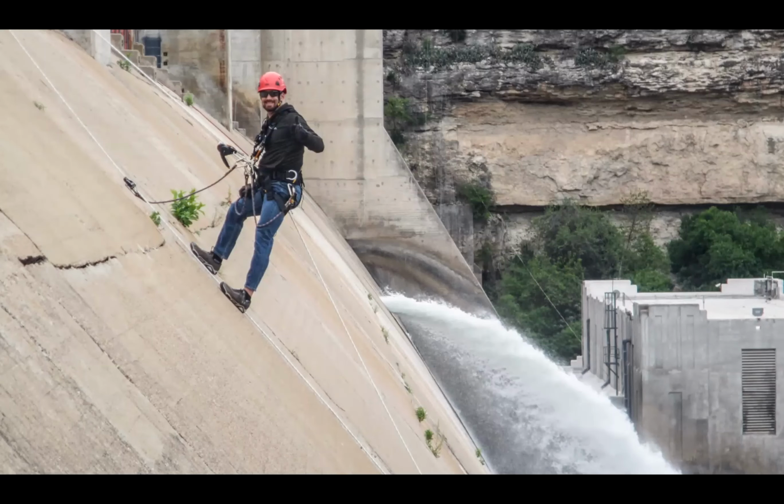And one thing of note in an inspection process like this is we're not necessarily looking at global stability of the dam. We're looking up close at all these different elements, but we need to remember that the dam itself is a very large rigid block. And so you have to look at the abutments. You have to look at, by way of survey, whether the dam is moving or not from a global stability standpoint. But in this particular photo, we're looking at the spillway, documenting different distress that's occurring. You can see the powerhouse in the background down below, and there's a little bit of release of water there.